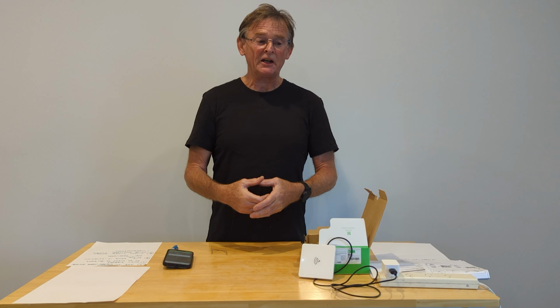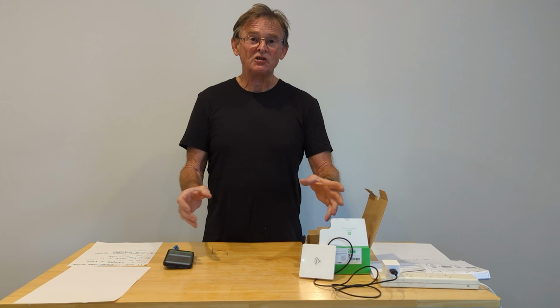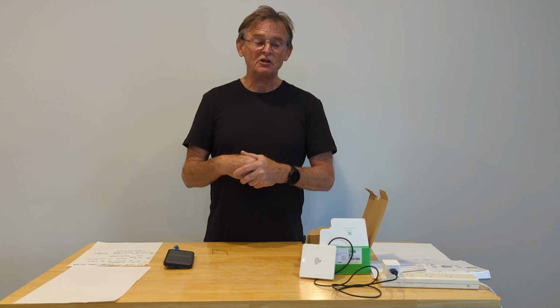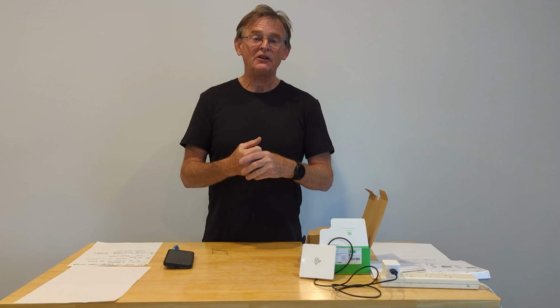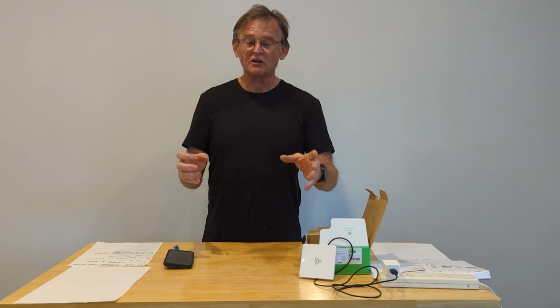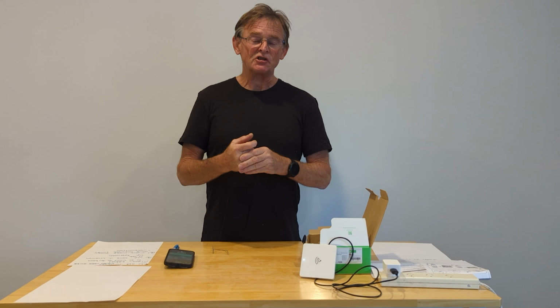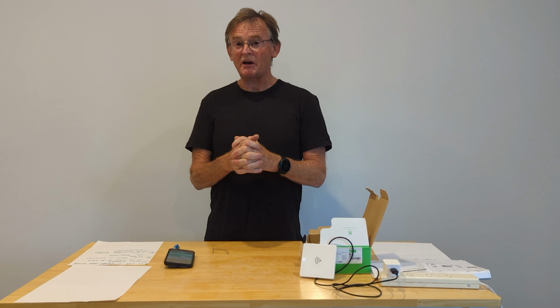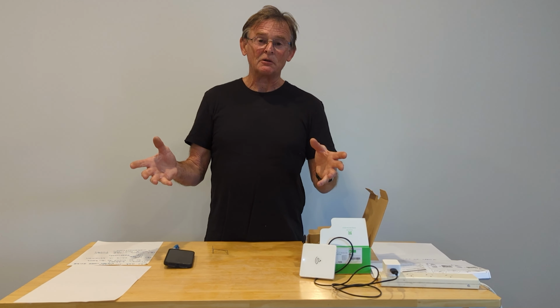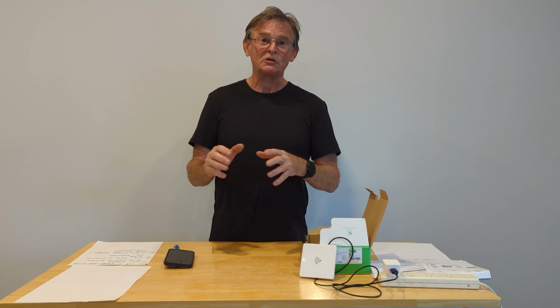The next video that we make, we will configure a light switch with a light on the bench and a two-way switch. And we're going to use the 10 amp mech and the 2 amp mech, probably separately and together. And we'll show the two-way switching or multi-way switching using the control wire that the Iconic range has. Because if we're designing a smart home, we want to make sure that our smart home is redundant. So when the Wi-Fi is not available, all our lights will still work from the switches.